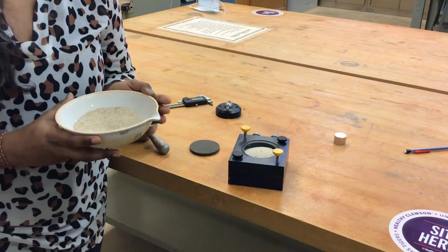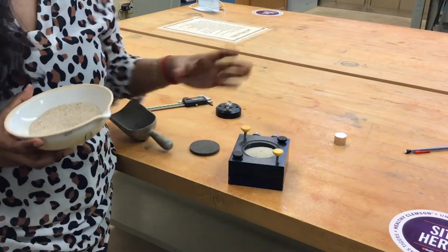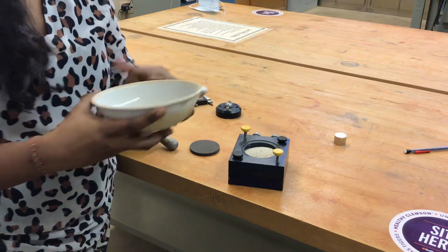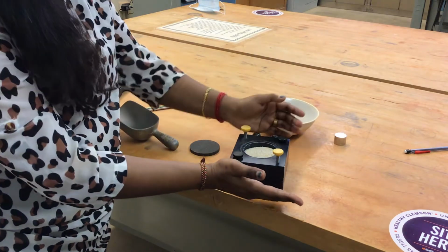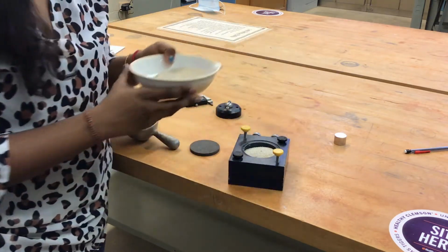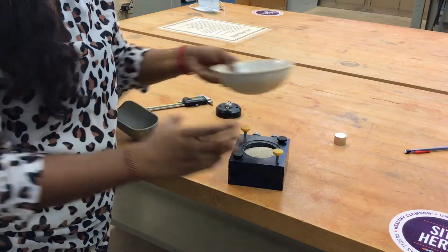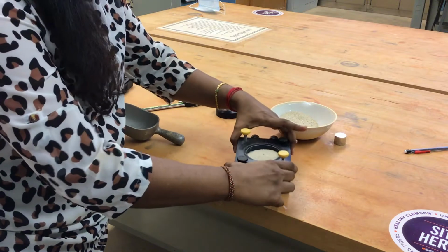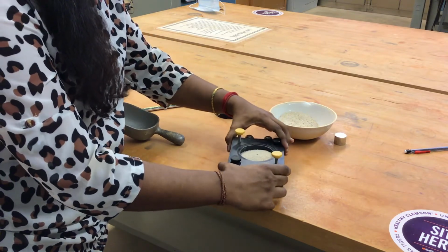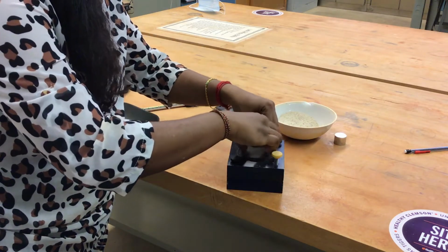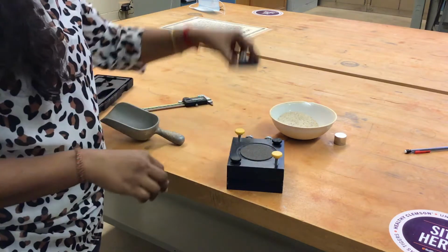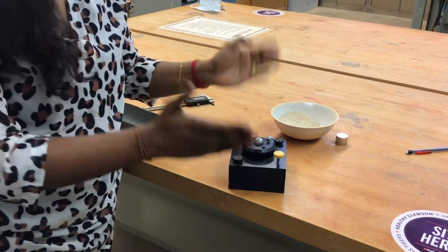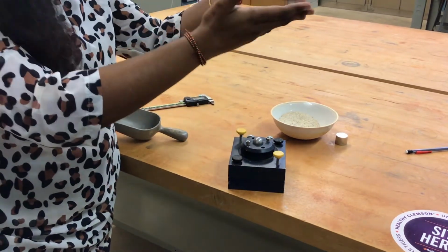So to get the weight of the soil that we are going to be using for the experiment, at the start you can measure the total weight of the sand, and then after adding to the specimen, you can measure the weight of the remaining sample. So finally you can find how much sand was filled inside the shearing. Then after adding the soil, I'm going to loosely compact it, and then I'm going to be placing the porous stone on the top. Then there will be a top part and I will have it there. So we have prepared the specimen, then we'll be moving to keep that in the computer.